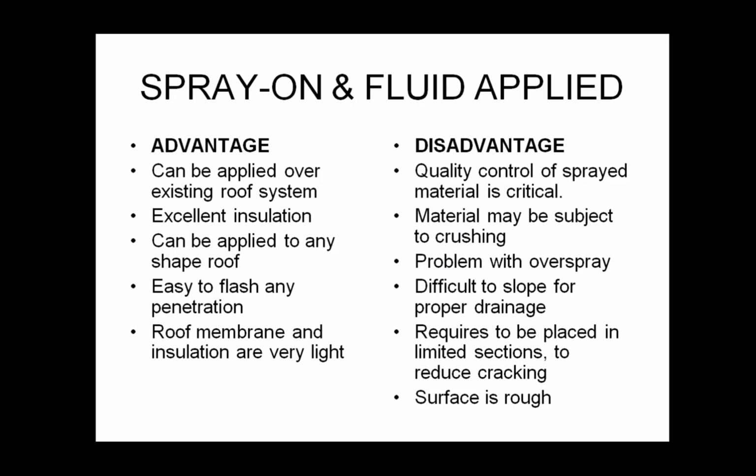You want to make sure that you have a very experienced crew that knows how to mix this material, and that they don't make any errors in the mix, because the mix is key to production. And again, the same with the experience level. You want it to be an experienced crew putting it on, so you're not overdoing the thickness, overdoing the material, spraying too much consistently in one location where it may be crushing or compacting that material so it doesn't work as well as it should. And then having that good crew will help prevent any other limitations in the application.